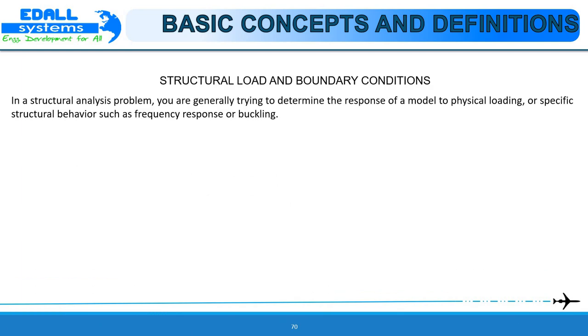Basic concepts and definitions. The following are several basic concepts and definitions that provide important information about the loads and boundary conditions application. Structural loads and boundary conditions. In a structural analysis problem, you are generally trying to determine the response of a model to physical loading or specific structural behavior such as frequency response or buckling. Some of the loads and boundary conditions that may apply include force, pressure, velocity, inertial loads, displacement, temperature, and contact.